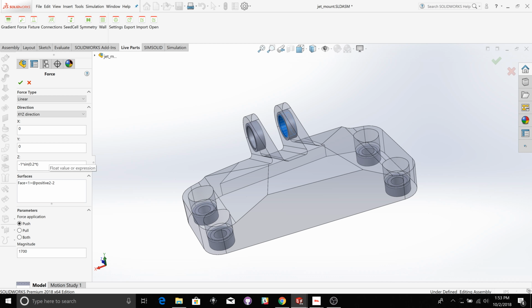What that's doing is it's causing the magnitude of the z component to switch back and forth from a -1 to a +1, and because this is a vector, it will be normalized. So what we'll end up with is basically an impulse where the force is going to shoot back and forth between -1 and 1 using the period of 0.2 times t. So that's how you can set up your forces to be dynamic.